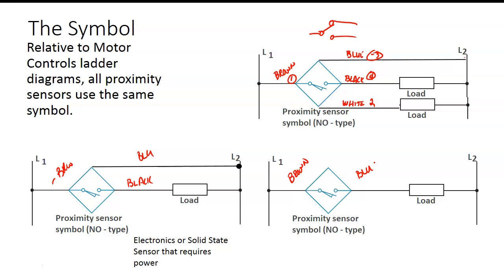So the first sensor that we're going to deal with is an inductive sensor, and it's going to be a 2-wire sensor. So it's going to power up through the load. So we can't hook a bunch of these 2-wire sensors up in series, right? You understand that? And why? One line goes up. Yeah. Well, that would be true of any of these. So if this sensor died, then everything would be dead. That's the point. But that's not why we can't hook a bunch of these 2-wire sensors in series. And why is that?